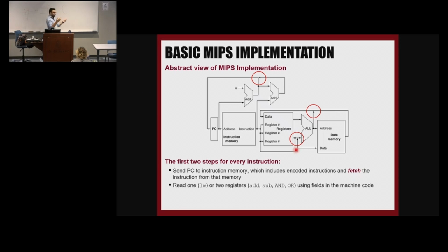Now if we have 4 inputs with 2 select lines, we can connect different paths. If I choose 0, 0, the first input is connected; 0, 1, the next one; 1, 0, the next one; 1, 1, the last one. Okay, so a multiplexer works this way. There are a bunch of switches inside the multiplexers. We have simple transmission gates, which are made by transistors, of course, and they just connect the input to the output based on the selection.